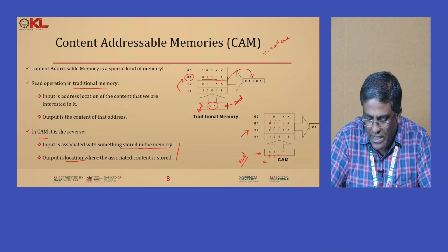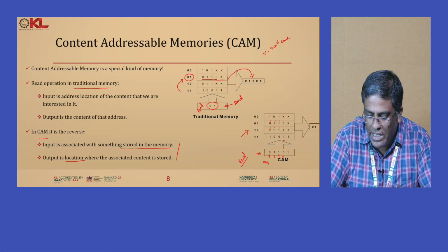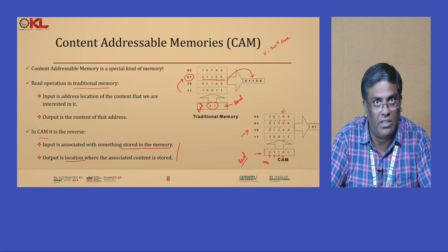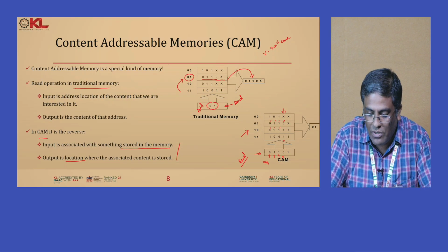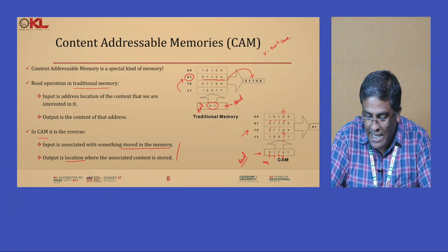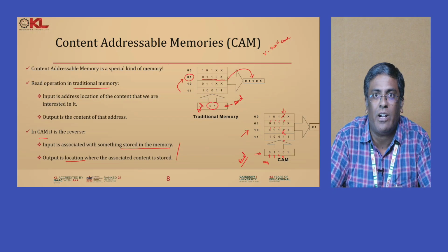We are starting from the MSB. Let me check the next condition. What is available? It is 0. And we are verifying where it is available. This is failed, it is not available. And here is the don't care condition, which means here it can be a 0 or it can be a 1. Both are possible. But in the case over here, 0 is available. It's exactly matching the content we are searching, because 0 is available, right? So 0 is available over here, and here also it's going to be either 0 or 1. Only half of the chances we have. So in this case these both will be eliminated because they are not going to be selected.